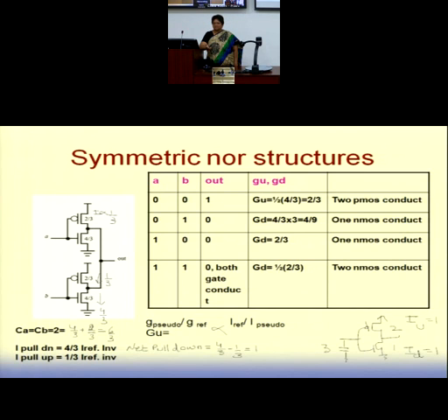I standard is 1, divided by how much? 1 by 3 plus 1 by 3, which is 2 by 3. Divided into 1, it comes out to be 3 by 2. Naturally, it is more than 1. It has to be more than 1 because there are 2 gates, each having a degraded drive capability.